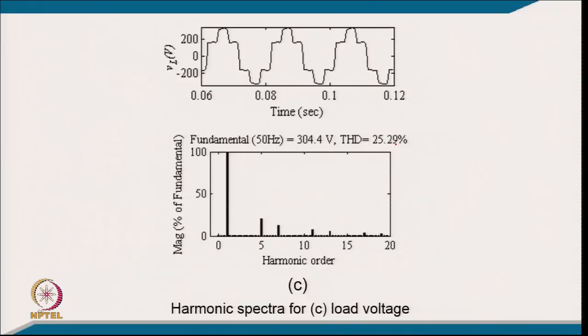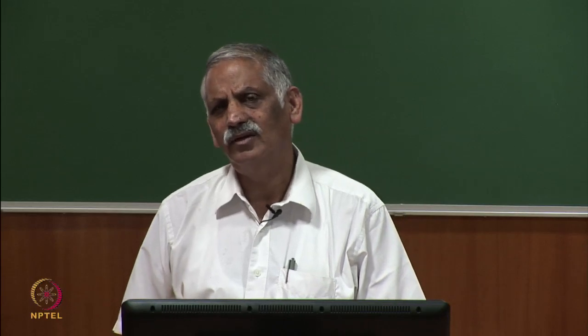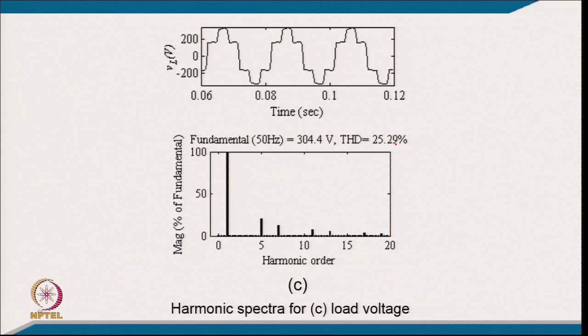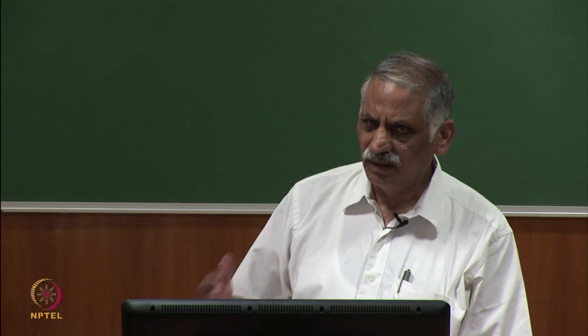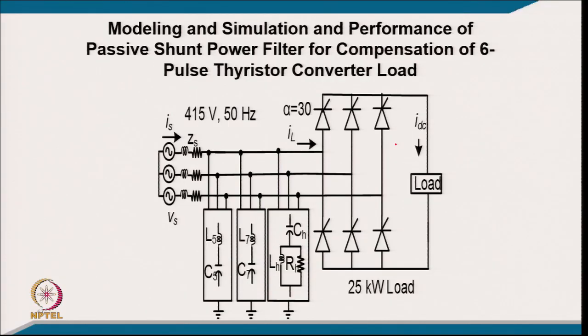So you can correlate; this covers reasonably the concepts of power electronics in all these circuits, because it is a power electronic circuit, including the THD at the load voltage. But this is not going to affect the load in any way, because the capacitor is now charging more effectively by all 3 phases. Earlier it was charging by only 2 phases, with current flowing from one phase and returning to another, and sometimes the current was not flowing at all. So now you will find the ripple on the capacitor voltage is also less. That is the benefit.